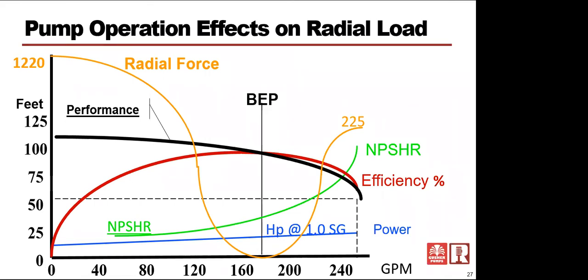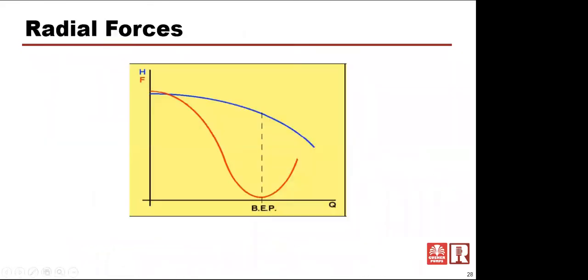One of the first things that happens as we're running off the curve in either direction, if it's a sealed pump, is we may have enough shaft movement to cause that mechanical seal to fail prematurely. A mechanical seal really depends on smooth operation for the faces to be able to come together. A typical mechanical seal has one rotating face that rotates with the shaft and a stationary face that's stationary in the pump casing itself. Those two are riding on each other.